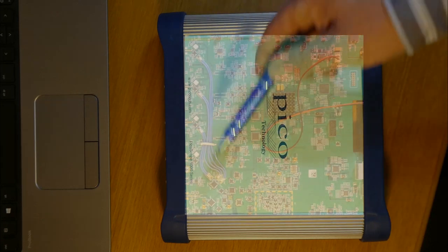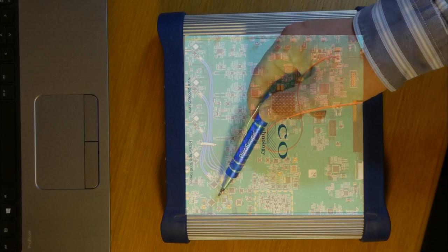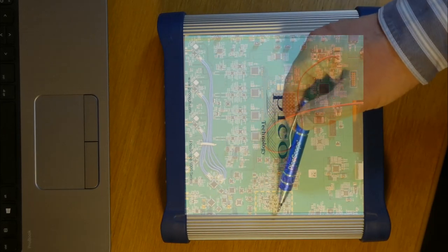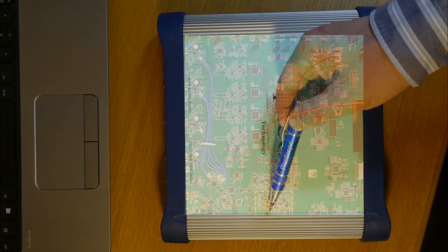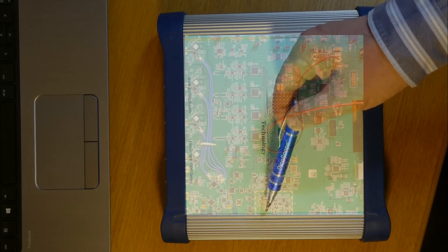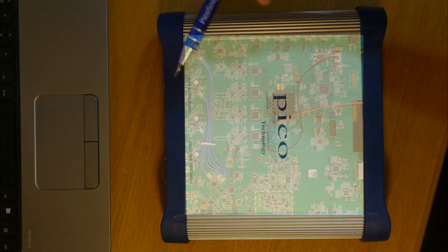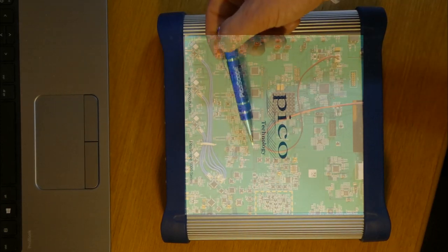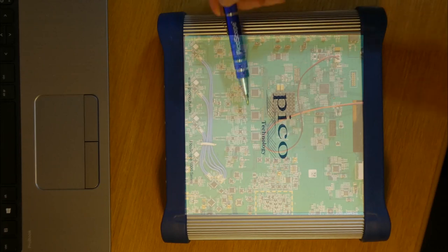We have trigger receivers down here, master sampling clock generation towards the center, and below our performance critical trigger to clock phase determination. A little set back from each channel, A to D drive amplifiers and the 4 500 megasample per second 12-bit A to D converters.